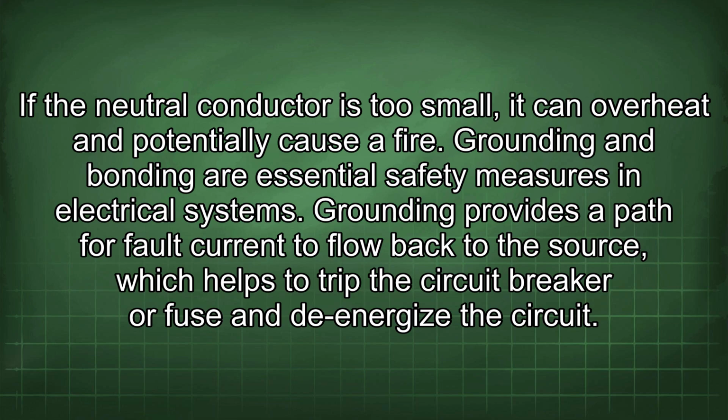Grounding and bonding are essential safety measures in electrical systems. Grounding provides a path for fault current to flow back to the source, which helps to trip the circuit breaker or fuse and to de-energize the circuit.